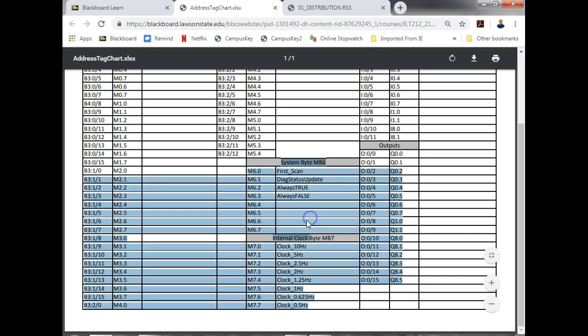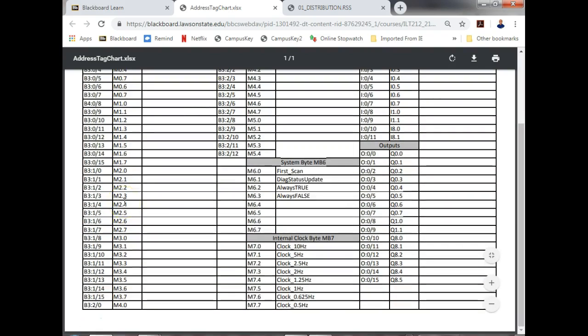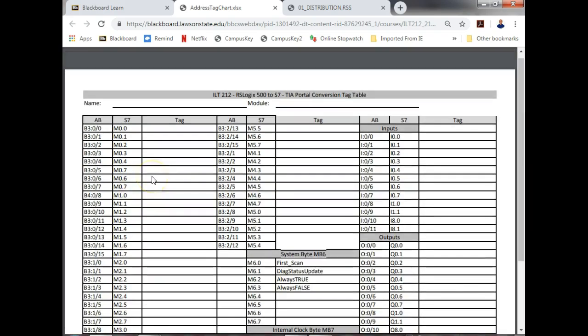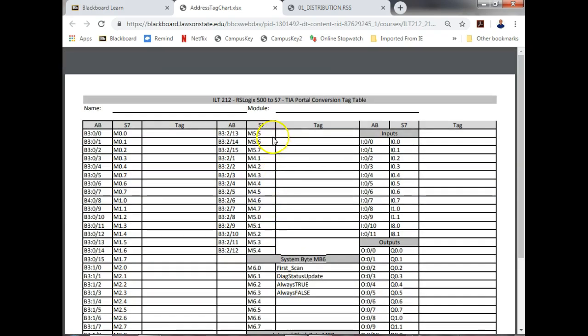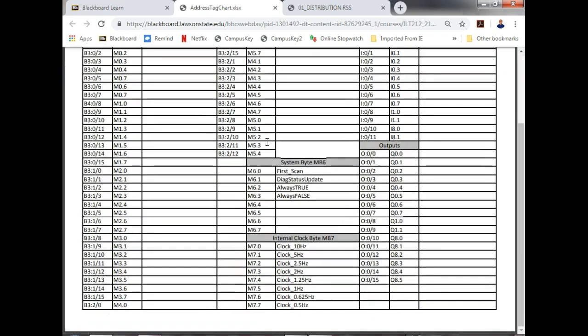So in the Allen Bradley software, you're given a B3 file. In the Siemens, they're not assigning any memory. They only assign memory when you need it, right? You understand? So on the new PLCs, you control the memory. In the older PLCs, the application controlled the memory. So remember, Allen Bradley had counters, so you don't see any counters in here. It wouldn't even create a data block until you created your first counter. So we'll go back and look at that.